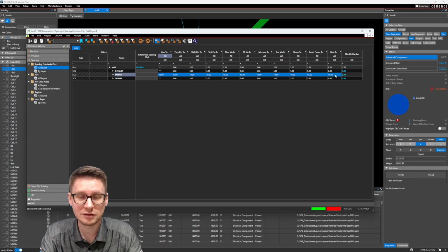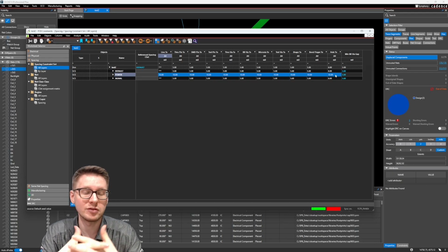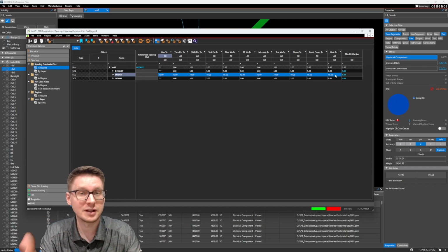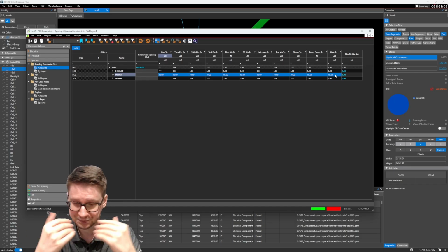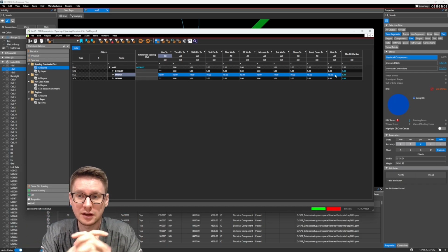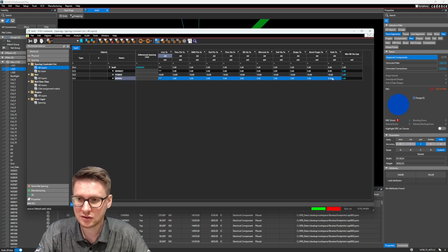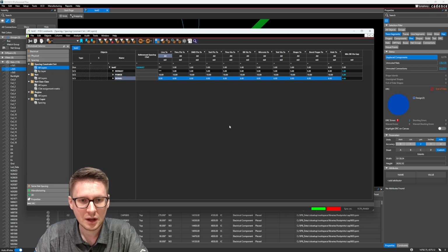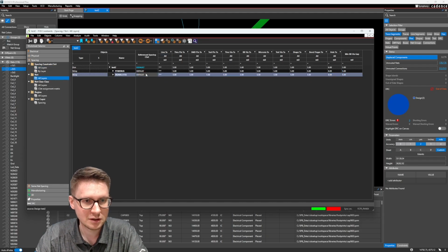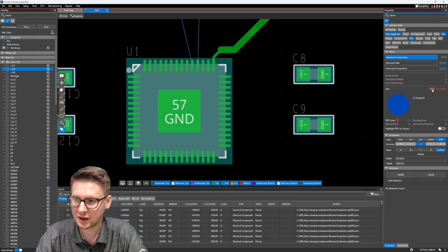I'm just using kind of a value that sounds about right for now. If you have different requirements for your own board, or you're working with a manufacturer that allows for slightly tighter spacing, by all means, feel free to set that in your design. But in my signal here, I'm also going to set this to 6 mil across the board. And we will say that this is good. And then just set my power to power and signal to signal. And then let's see what we get when we update our DRC.